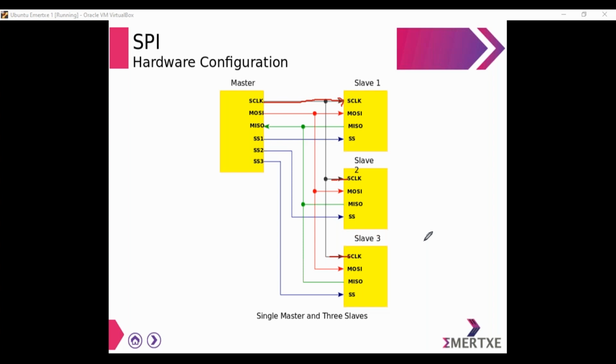Yes, that is possible, but it has to be on the same board, connected on one PCB. External in the sense it may not be available inside your microcontroller, so you connect it externally, but it has to be on the same board. For example, on a breadboard, you connect the microcontroller and the sensor of your choice. That is possible.